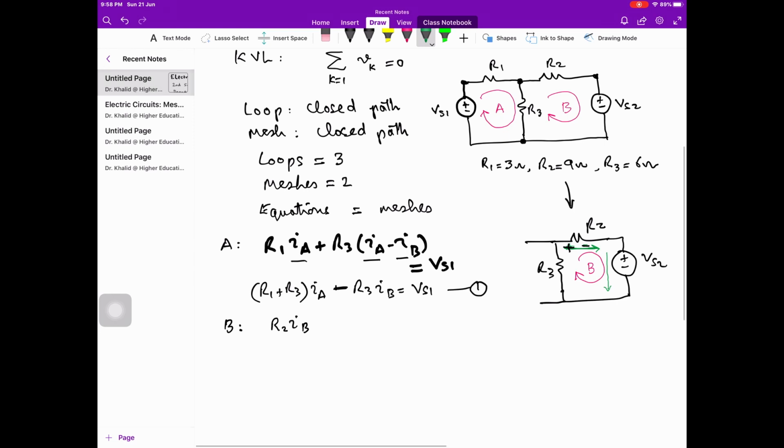So here we see that the sign of the first side of this voltage source is positive. This is also a voltage drop. Therefore, if we go from positive to negative, it is a voltage drop, and if we go from negative to positive, it is a voltage rise. So this is a voltage drop, so I will write it along with the voltage drops across each element.